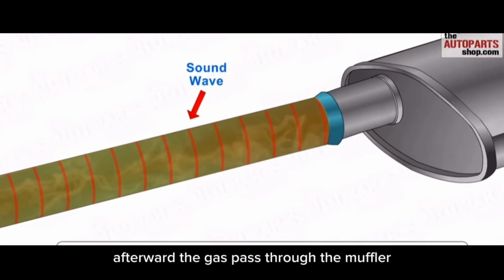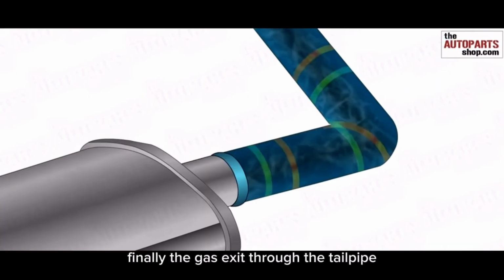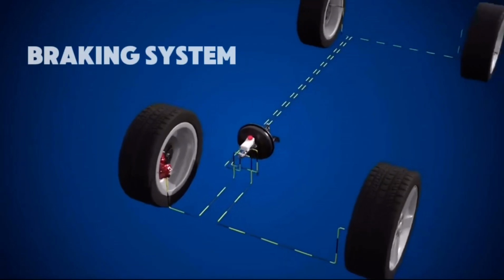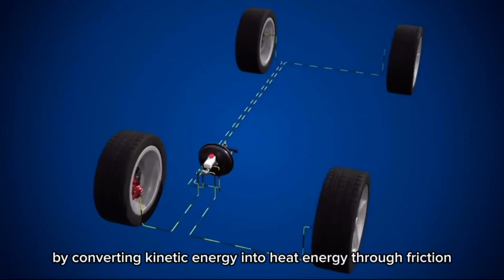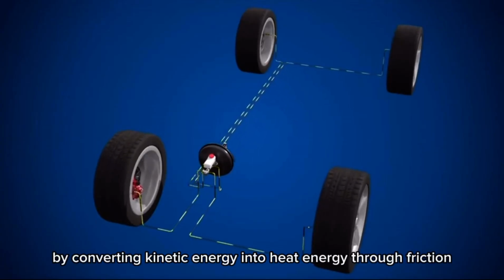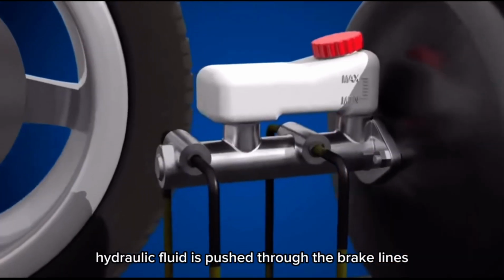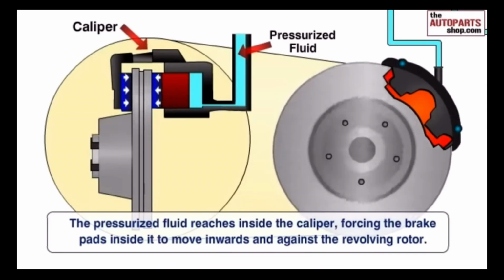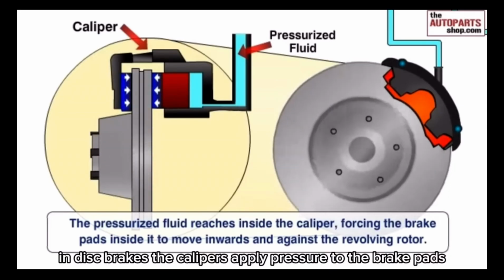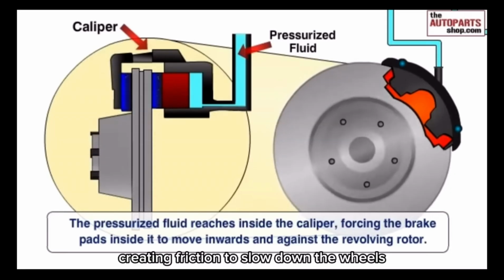Afterward, the gases pass through the muffler, which reduces engine noise by damping sound waves produced during exhaust flow. Finally, the gas exits through the tailpipe. The braking system is vital for controlling the car's speed and ensuring safety by converting kinetic energy into heat energy through friction. When the driver presses the brake pedal, hydraulic fluid is pushed through the brake lines to activate the brake calipers. In disc brakes, the calipers apply pressure to the brake pads which clamp onto the rotors, creating friction to slow down the wheels.